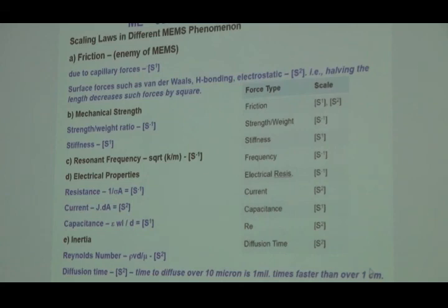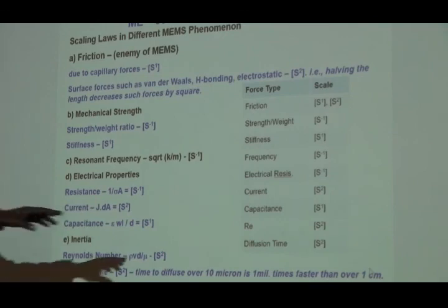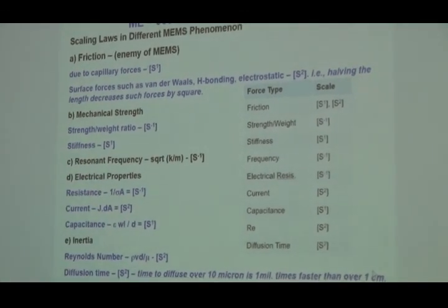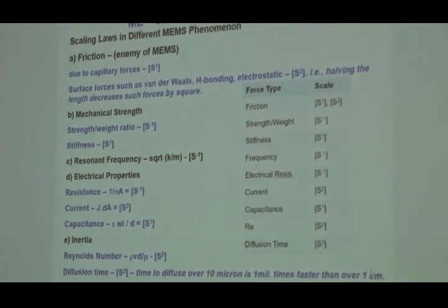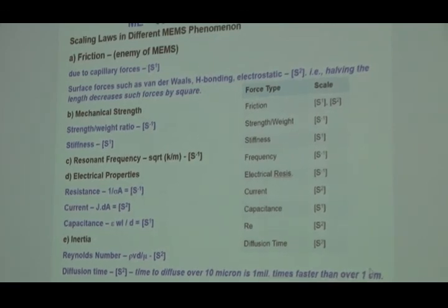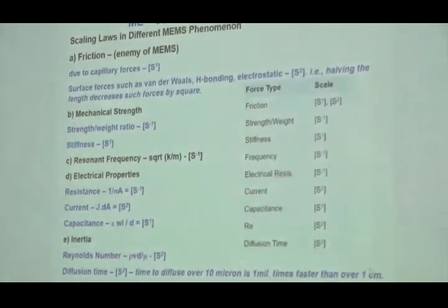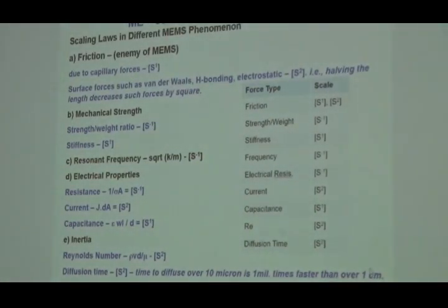Now, the biggest mystery in microfluidics is when you pass liquids in a small channel, as you reduce the size, the Reynolds number also reduces in a quadratic fashion. You reduce the size 100 times, the Reynolds number reduces by 10 to the power 4, 10,000 times. Absolutely remember this: in microfluidics you will never have a turbulent flow. In fact, it's a big headache. It's all laminar, with a Reynolds number of 10, maximum 100.